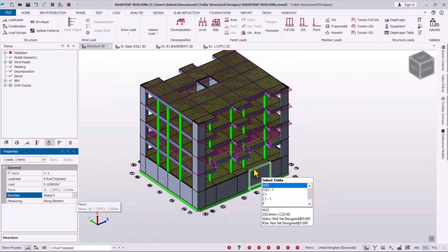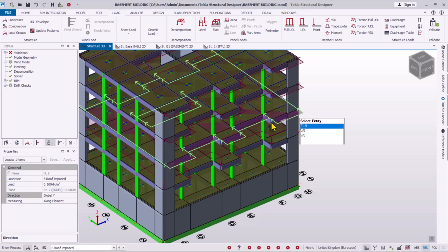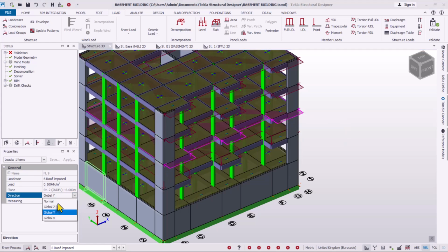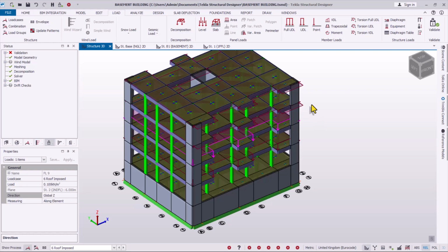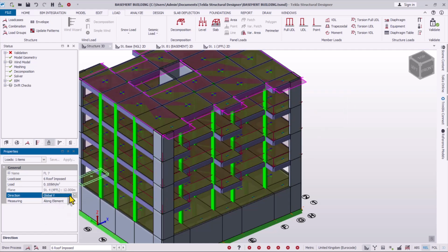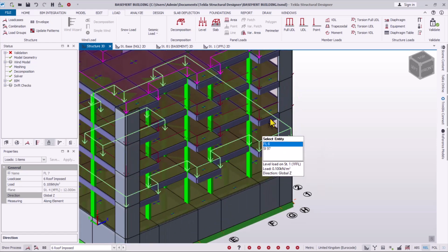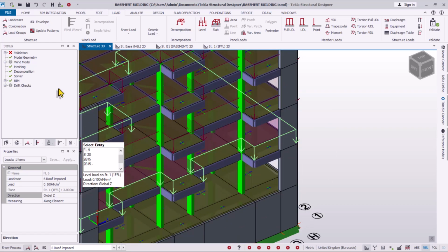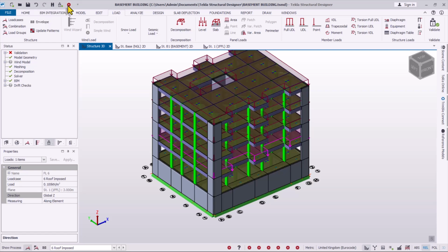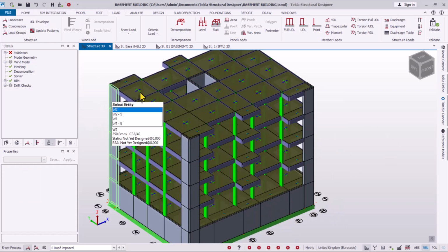You see, that has changed at this floor. So you have to select it at this floor, and as well change it here to the Z directions. Select on this, change it to global Z directions, and then over here the same thing, change it to global Z direction, just like this. So you can as well select on this. If you try to delete this, you see all the load is gone. The roof imposed is gone because the stories are similar.